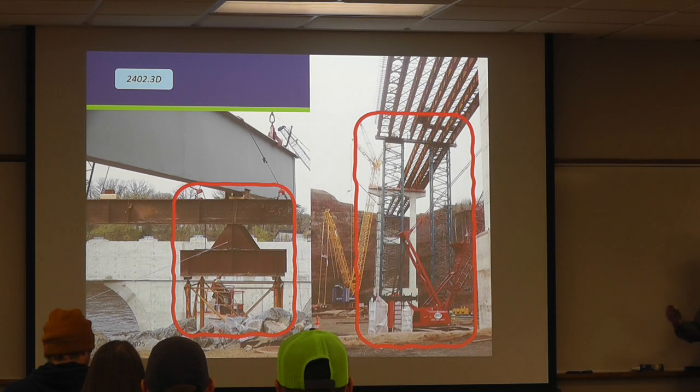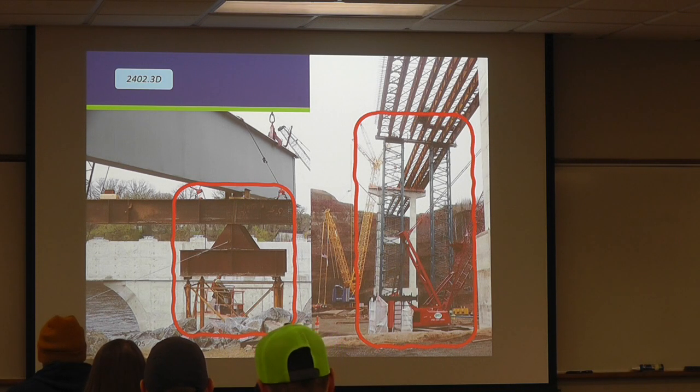So that's where I really emphasize the safety piece of this. You don't have to be an expert in this, but if it says there's supposed to be a 100-ton shoring tower out there, it's probably a good thing to just go verify that before they hang the steel. Does that make sense? Susan?